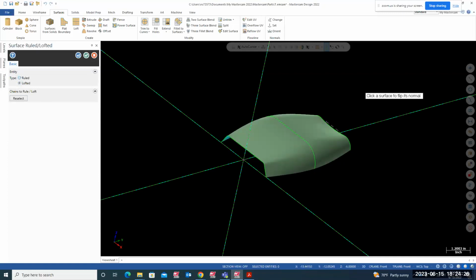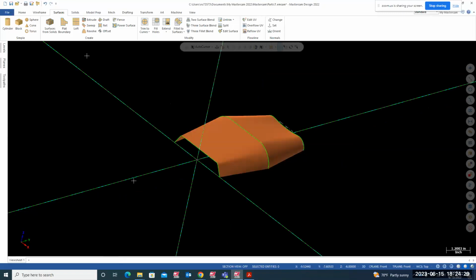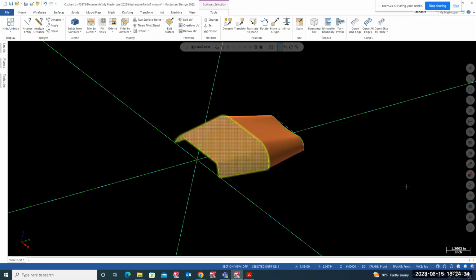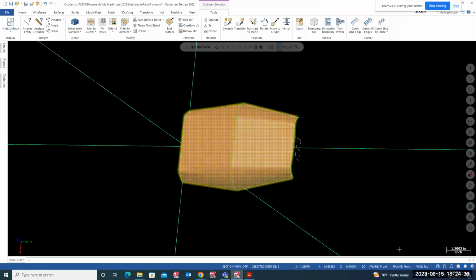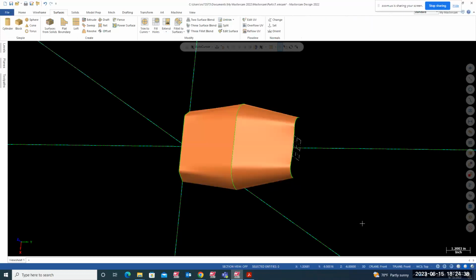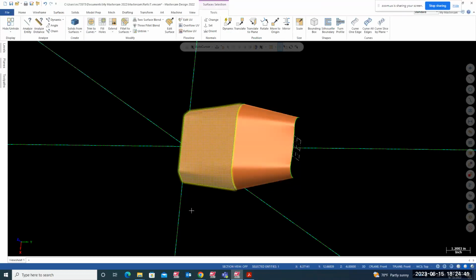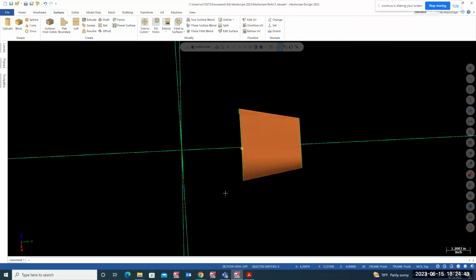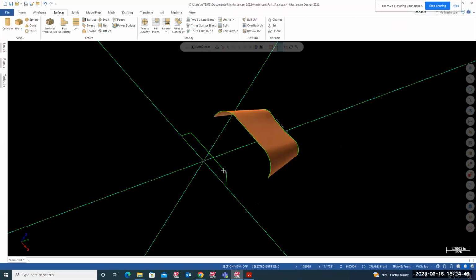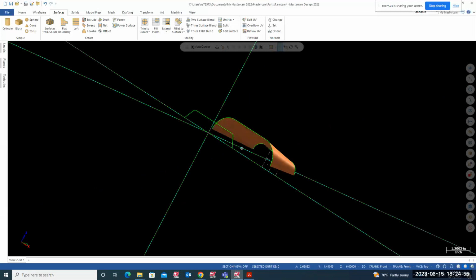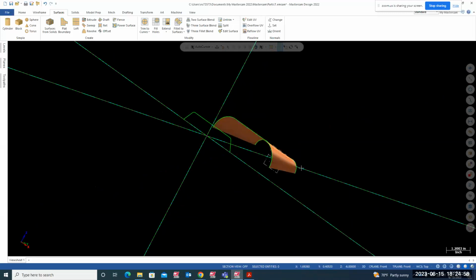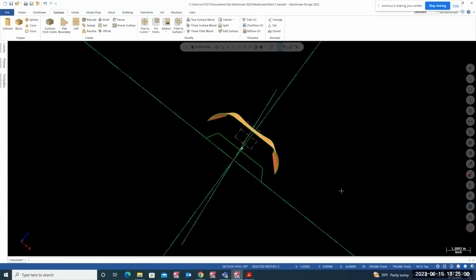When you say ruled and you hit OK, like I said, ruled is a surface between this geometry and this geometry. So the ruled has one individual surface here and another individual surface here. Hit the escape key. If you want to delete one, you can individually delete that. So under rule, each chain has individual surfaces between those two chains. You have to have two chains at least. But the surface is going to be a linear surface, like a straight line. It's mostly straight, called linear.